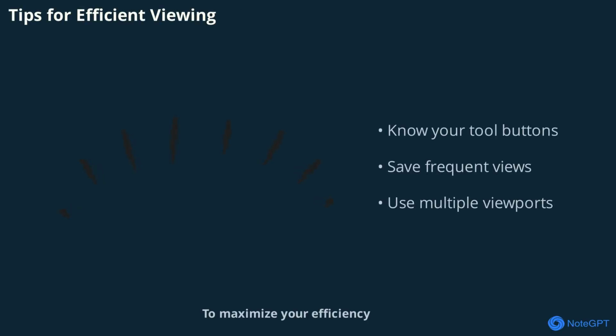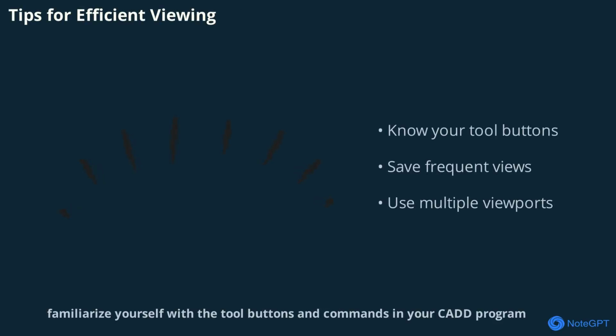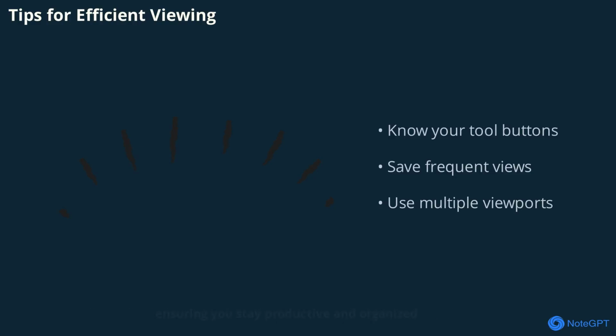Maximize your efficiency. Familiarize yourself with the tool buttons and commands in your CADD program. Use real-time pan and zoom for quick adjustments, save frequently used views, and take advantage of multiple viewports for complex projects. These tips help you navigate large and detailed drawings with ease, ensuring you stay productive and organized.